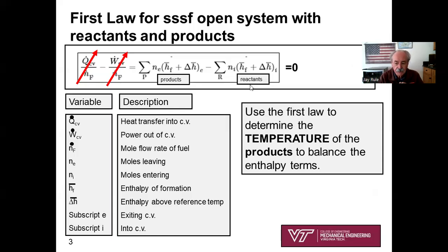And what's your proposed combustion process? Well, you're going to propose that you have C_m H_n, and you're going to propose a certain amount of excess air. It might be 0, or stoichiometric, or it might be 10% excess air. It might be 100% excess air. Does your common sense tell you that as you increase the percent excess air, your adiabatic flame temperature will be a lower number, because all you're doing is heating up excess air in the process?